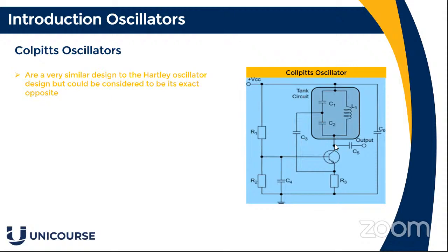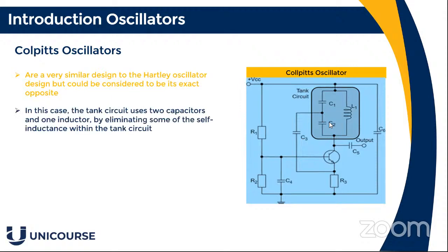Same as before, it's fed into the collector of this little one-stage amplifier, and instead of tapping the coil, you tap the capacitor. And it's quite a stable little circuit, and I've used them years ago as part of a little radio transmitter. What quite often we did is it produced an RF frequency, but we couldn't really apply audio to it. So what we used it for was what was known as Morse, so we could link into the actual RF side of it, and then we can send out Morse signals.